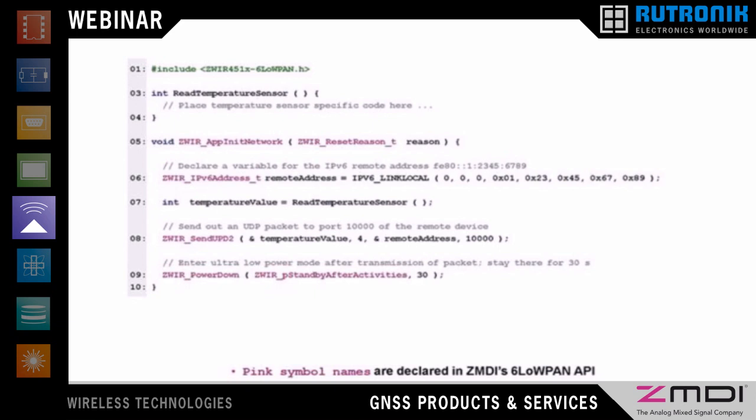So as I described before, we have 3 different gateways. They are all working completely transparent. So if you attach a gateway to your given network, you can ping the modules, you can communicate with the modules without thinking about address translation or something else. So the Ethernet gateway is completely independent from the operating system, and it can be just added to a normal switch or a router.